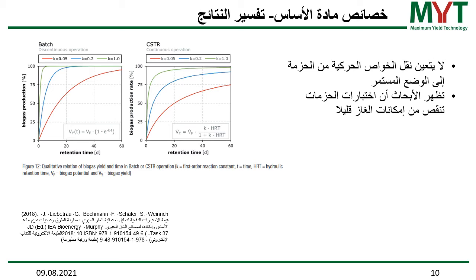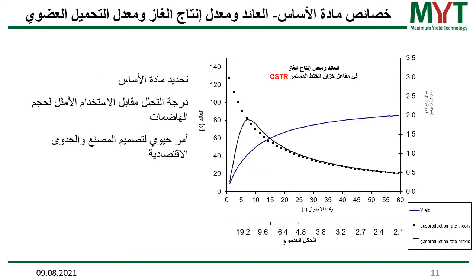Research comparison has been showing that batch tests tend to slightly underestimate the gas potential compared to a CSTR system. You find this in the reference I have given to you here in this slide. There are some results compared. So it's difficult to give really a comprehensive picture here, but as said, the batch tests tend to rather underestimate full-scale or continuous testing results.